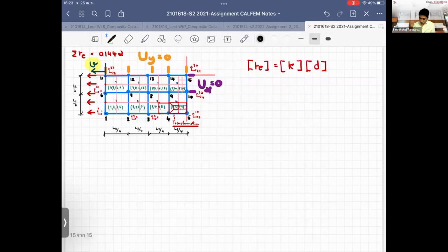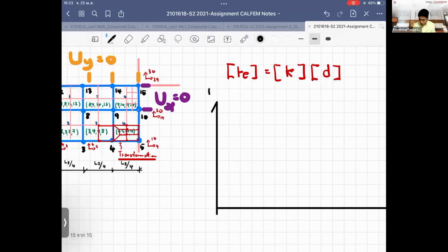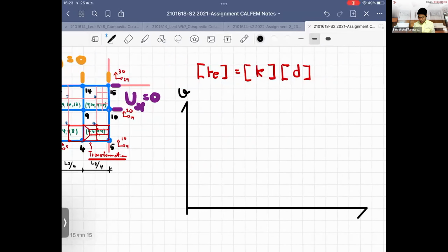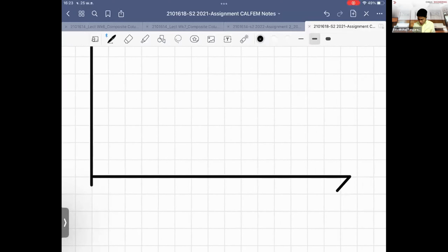So to make sure that you can obtain accurate values, you should test the element. The way we test the element is that in this exercise, we suggest you use the displacement value at some specific degree of freedom. And in this assignment, we told you to plot them versus the number of elements you use, or the finite element number you use.